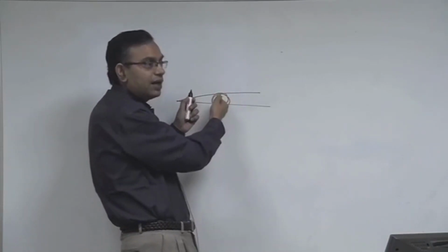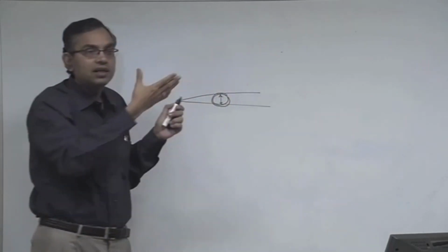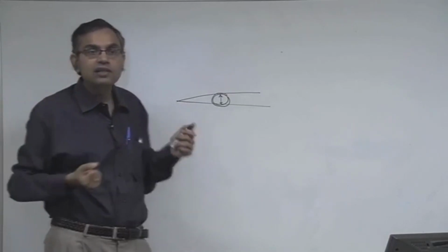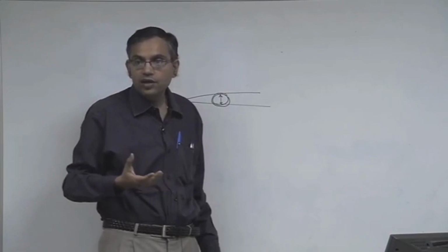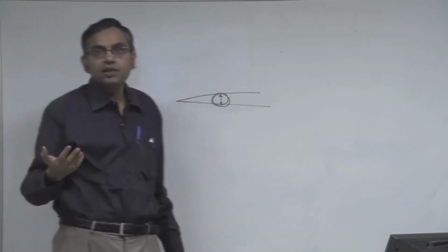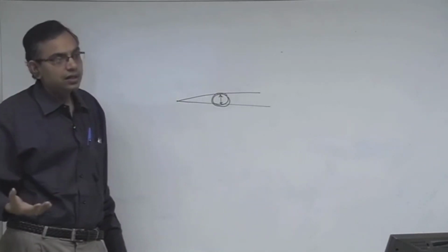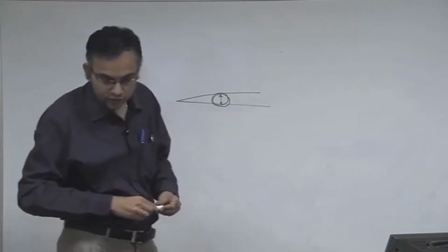By putting a magnifying glass, you have magnified or stretched the boundary layer region and have applied a transformation to achieve that stretching. This is called a stretching transformation. Okay. So, this singular perturbation theory is commonly used to analyze the boundary layer type of flows. So, singular perturbation is also important.